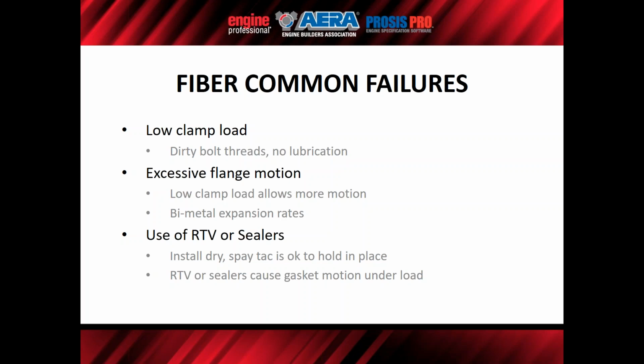You should put lubrication on there, the engine oil. That lubrication reduces the coefficient of friction, which gives you better clamping, more load. So again, low clamp load is one of the common problems with it. Excessive flange motion becomes another issue. That low clamp load allows more motion.